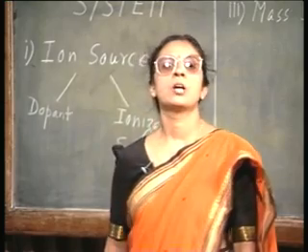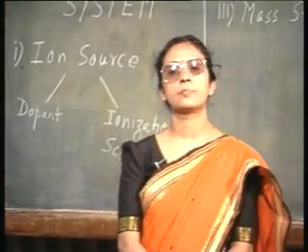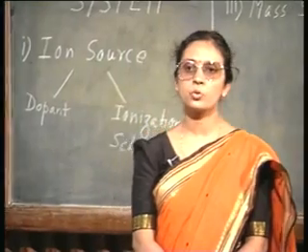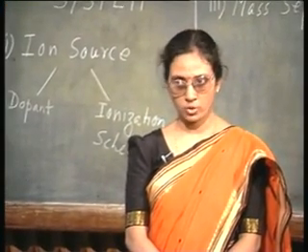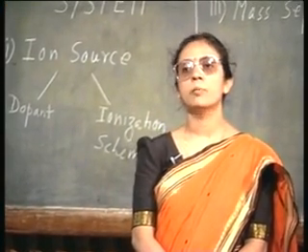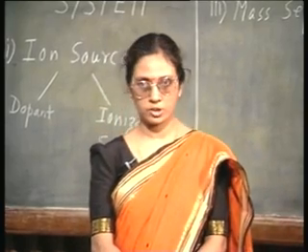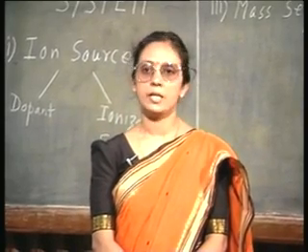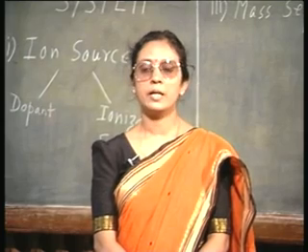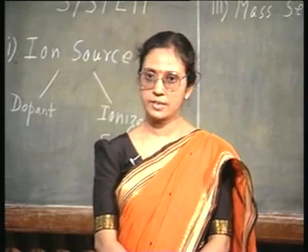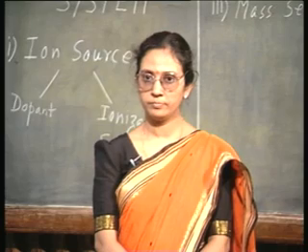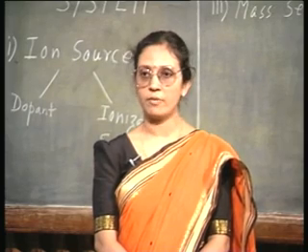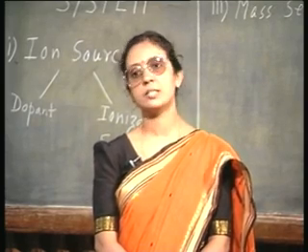But remember, we said that ion implantation is a process much less prone to contamination. Okay. Now, you have used a compound of the dopant species and you have ionized this. So, there are various ions in this ion stream, possibility of having various type of ions in this ion stream.